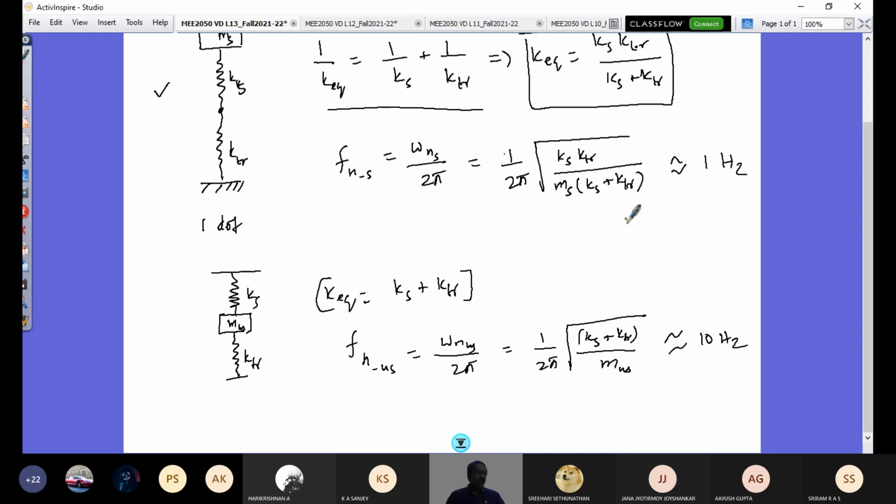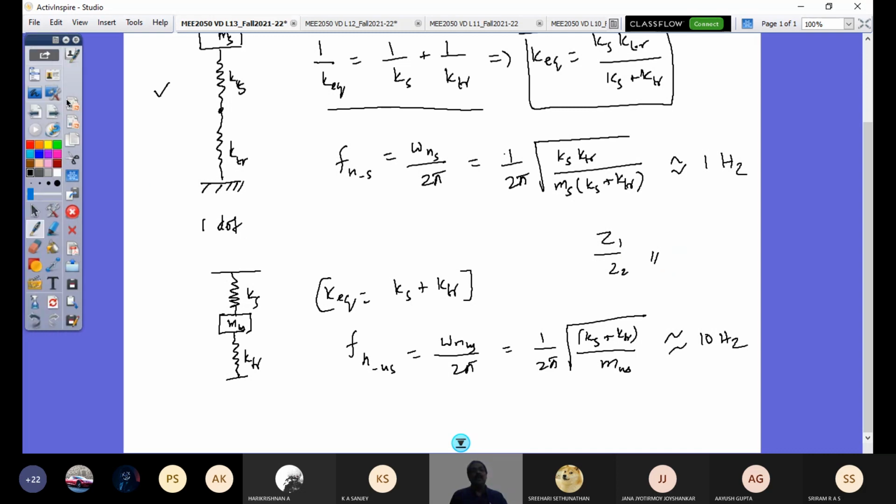That is the reason why you can have such an approximation, and we have to follow some of the implications. So the amplitude ratio Z1 by Z2 can be obtained from equations number 4 and 5, I think, from the last class. So you can use that and find out. But this is not of our interest. What is of our interest is Z1 for the given road input excitation, or the road profile Z0, or Z2 by Z0. So for that I have to extend my analysis looking at the equation further with the quarter car model, right? Again, going back to your 2-degree freedom model.